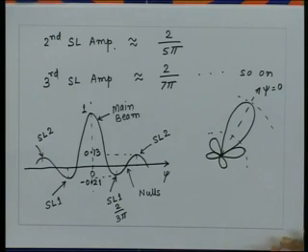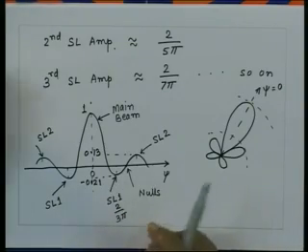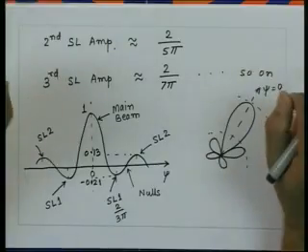So, the interesting thing which we note from this is that the level of the side lobe is not dependent on any of the array parameters. For example, we had 3 array parameters which were identified: the number of elements in the array, the progressive phase shift of the array, and the inter-element spacing of the array. The progressive phase shift decided the direction of the maximum radiation.